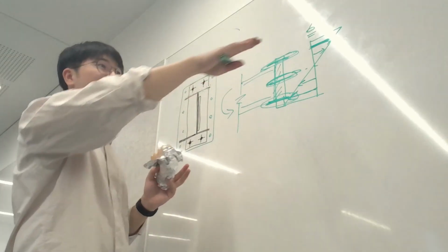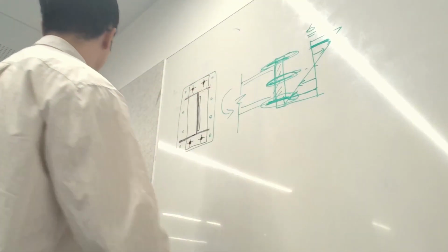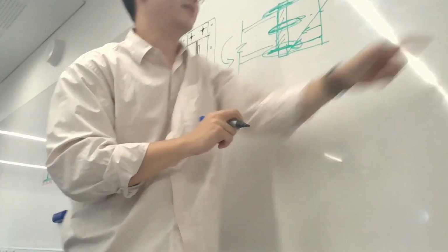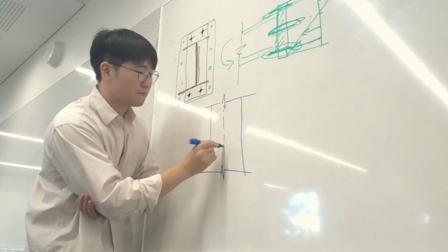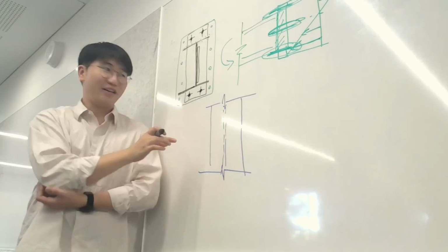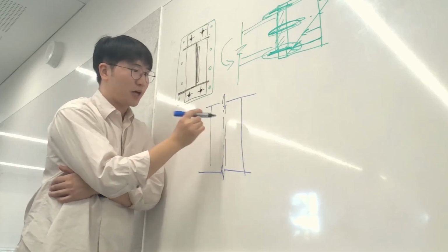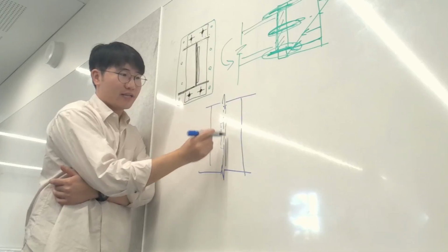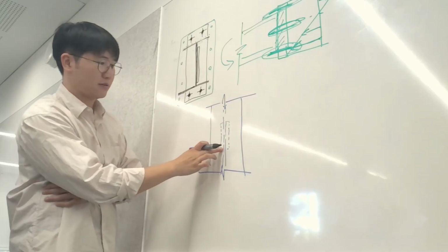Okay, let's go back to this whole thing. The way that I would detail it, I'll draw it down here. The way that I would detail this dashed line, and I zoom in, so this is the top flange of your I-beam. The dashed line is the web. Now, this is your beam running north-south, or whatever. Now this web acts as a wall, so we need an end plate underneath it. Does that make sense? I might make this bigger.